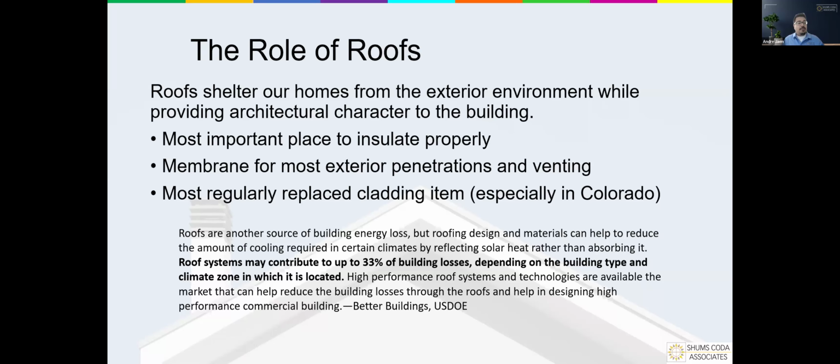And then there's also no doubting it as well. We've seen the effects of poor ventilation on the other side of that, where there's not enough, and then you see premature shingle failures. Colorado's definitely been a place where you can highlight a lot of those, where you get these brittle asphalt shingles and things because of a lack of ventilation, because of the wrong science basically being used and the wrong effect to be able to put this whole thing together. So great point, and we will consider that as we move along.